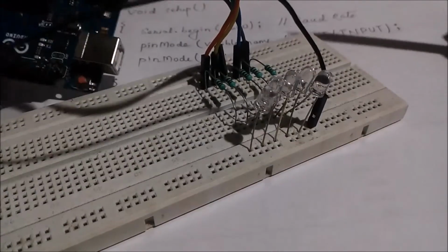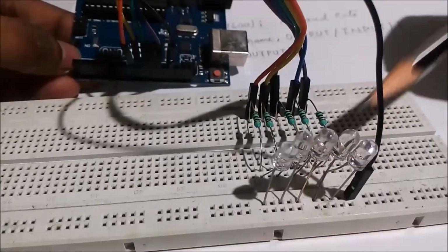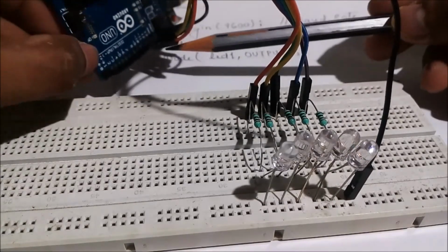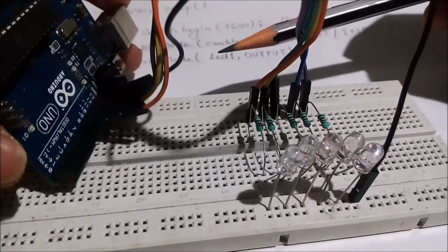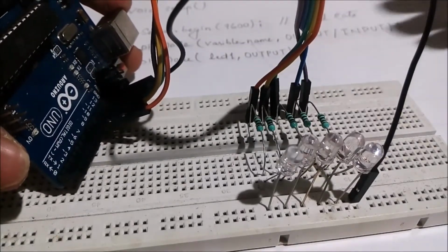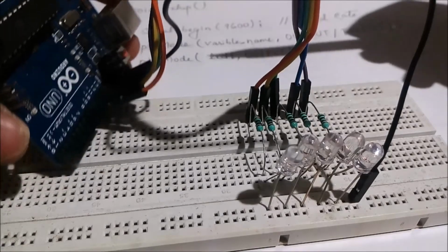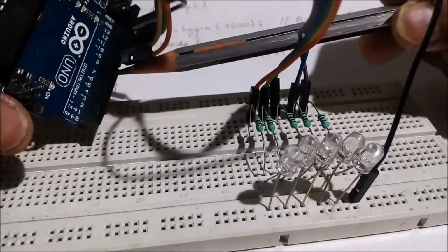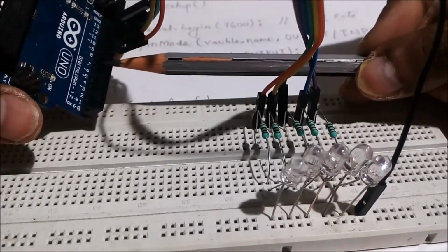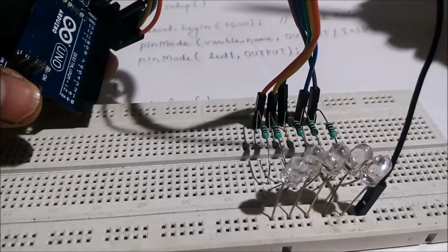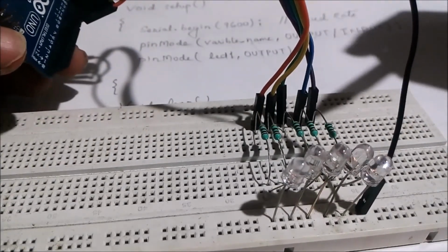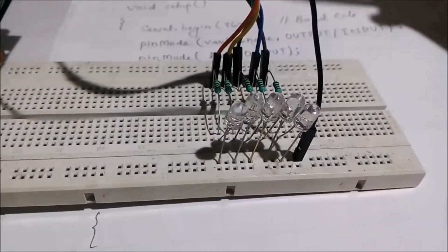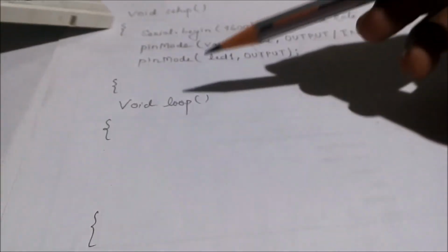Because as we connected the LEDs, we want to change the status of these pins as on, off, then after some time on, after some time off. So how can this be possible? This is only possible if pin numbers 8, 9 are turned on and off, then the LED will be blinking. Because it needs a continuous operation, these things are put in the void loop function.